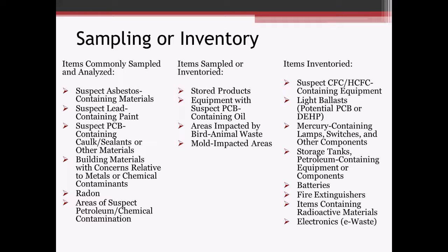So radon's a good one, maybe check up front as well. And then areas of suspect petroleum chemical contamination. This is more to do with your exterior areas. Do you have some tanks that might have leaked? It's good to go through and assess those, to make sure that when you go to excavate soil, you're not going to hit anything that you weren't aware of beforehand.